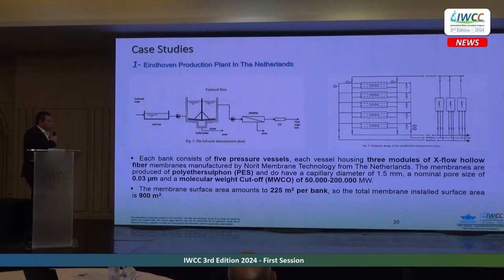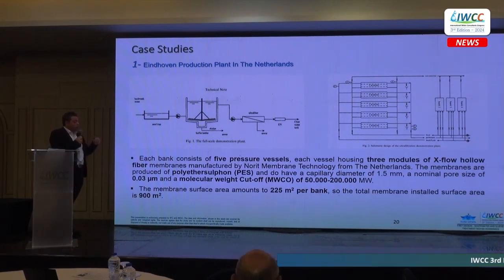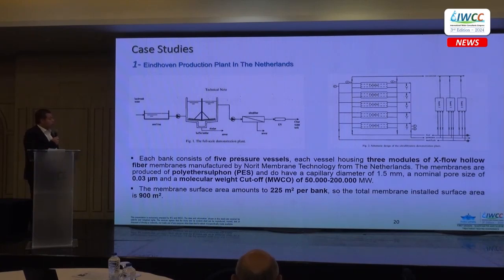Because they used pressurized ultrafiltration, they needed a clarifier before the pressurized ultrafiltration to reduce the amount of water needed for backwashing the ultrafiltration.